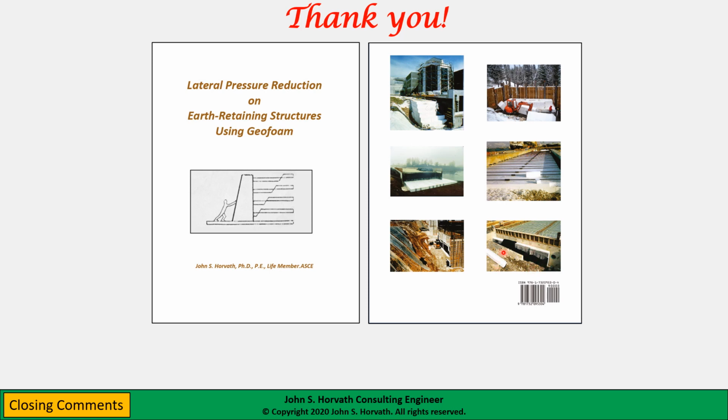So you see that the same composite product, the geotech geo-inclusion, is being used here. Again, 4 inches, 100 millimeters of resilient EPS, 2 inches, 50 millimeters of glued polystyrene porous block, and you see the dark colored non-woven geotextile. It's folded back here.